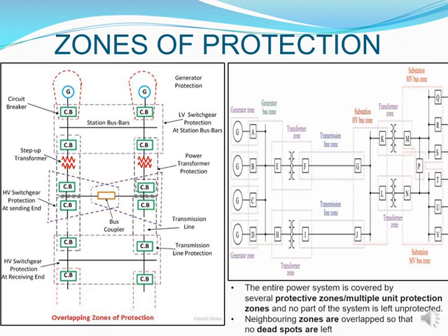Then you've got on either side the transformer zones. The transformer zones are looked after by E and F, and the other transformer zone by H and I. So again, if something happened on either one of those transformers, if it was the EF transformer, then those 2 circuit breakers would open up and that fault would be isolated. If it's the HI, then it would be those 2 circuit breakers that open up to isolate that fault.